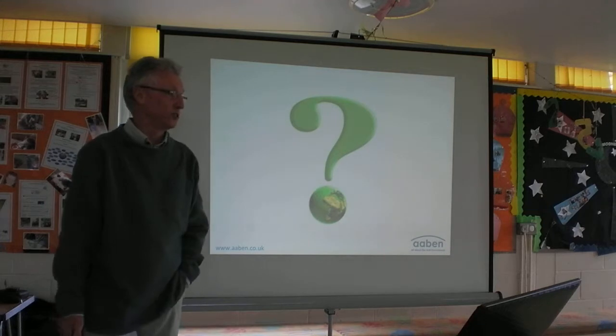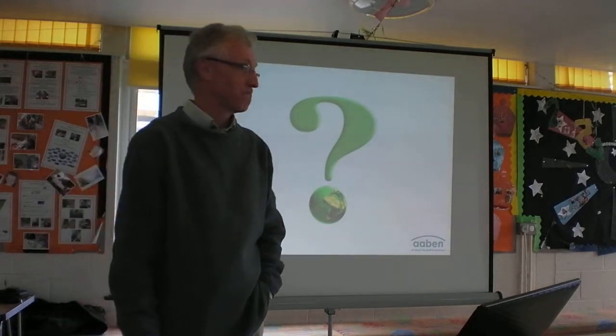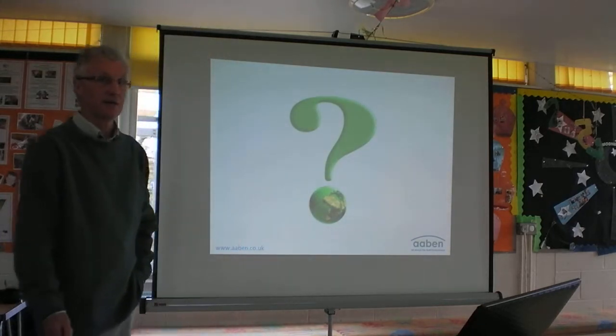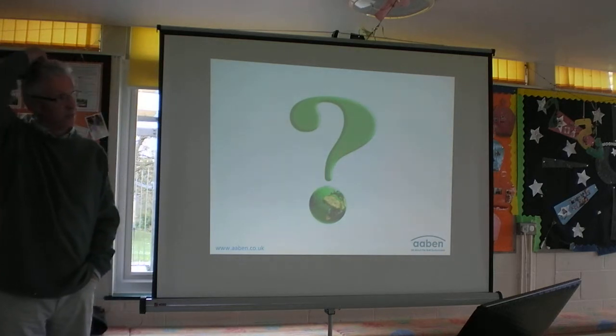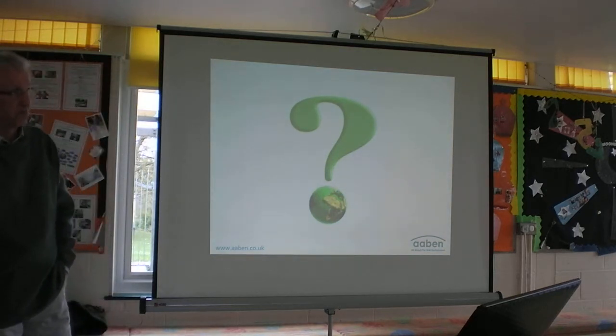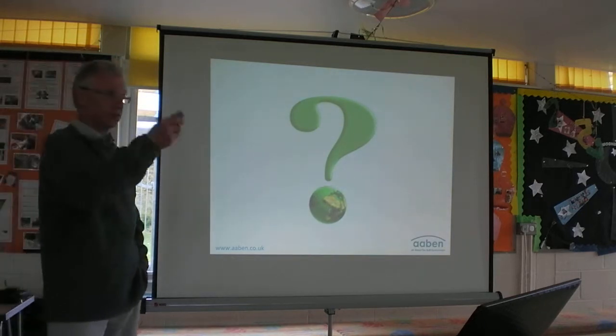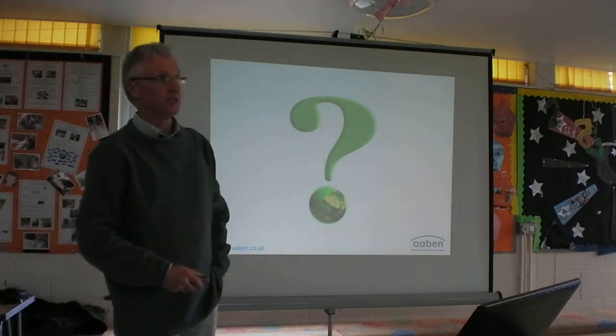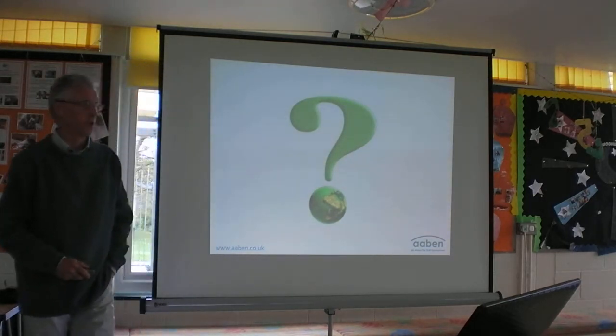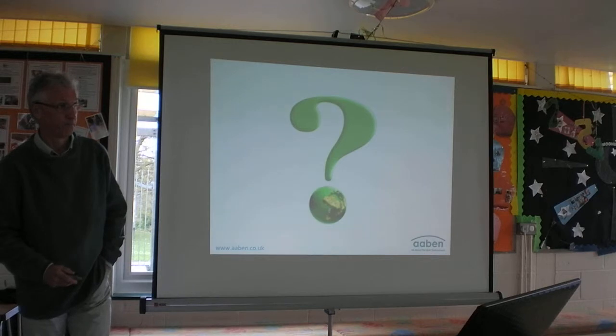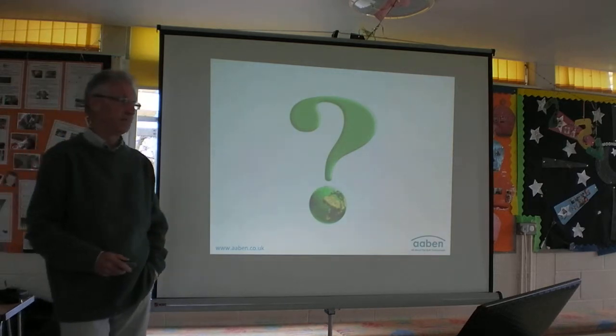Go and buy a country cottage, you'll get walls anything up to 1 metre thick, right? The last 50, 60, 70 years we've been building cavity walls 250, 300 thick. We've got used to 300 walls. A lot of designers and architects just draw 300 walls. You need to design a passive house with a 500 wall. You may be able to reduce on that, but if you start with a 500 wall, you can do it.